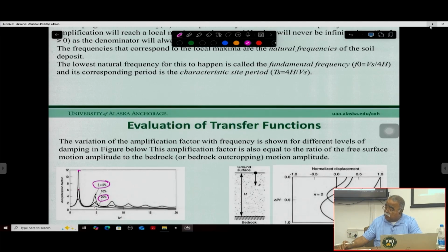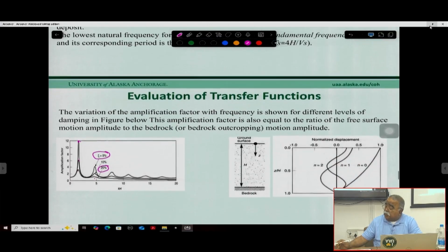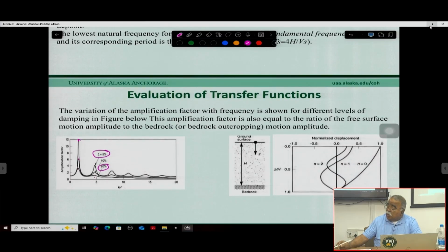Okay, so that amplitude you can calculate, right? So if you can see these things in a z by h plot, and this is the displacement or u value, you can see that as the damping becomes 0, the soil is displaced in the horizontal direction, because that's the u direction.